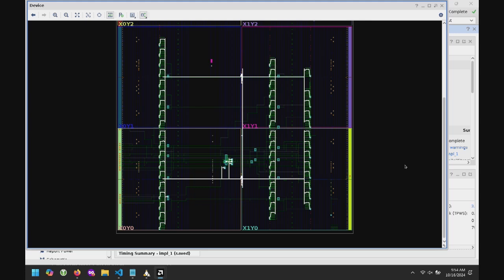Now let's imagine this clock signal that's oscillating, going from 1 to 0, 1, 0. When it switches to 1, how many flip-flops are going to have their value changed? Potentially all of them. If your design has maybe 100 flip-flops, it's the worst case scenario. All of a sudden you have this huge spike in power because your clock is oscillating. Every time it shoots up to 1 volt, every single flip-flop could charge up all at the same time. So what you get is crazy power spikes whenever your clock goes high.